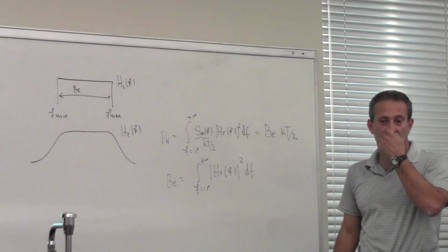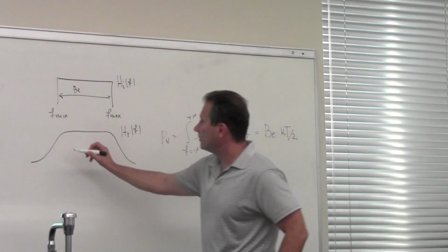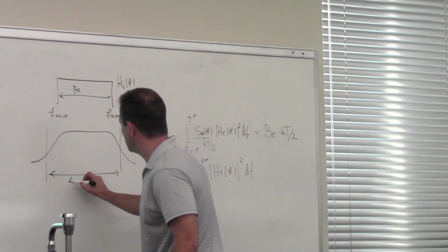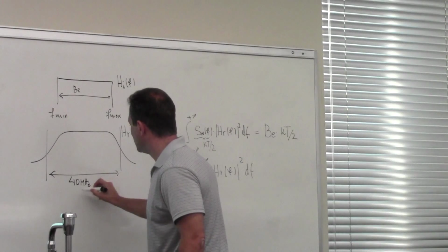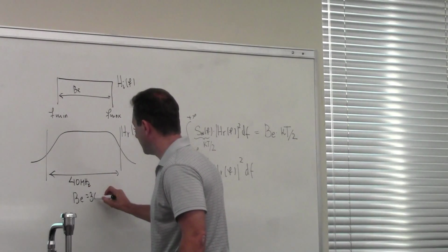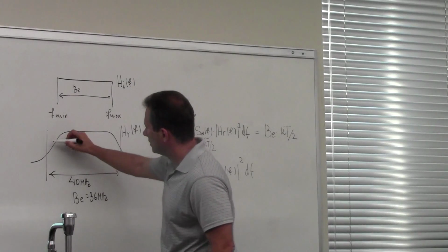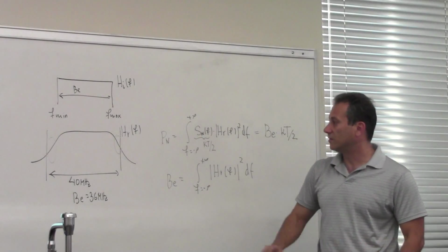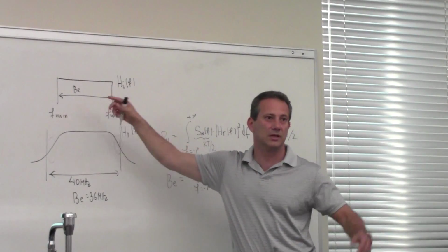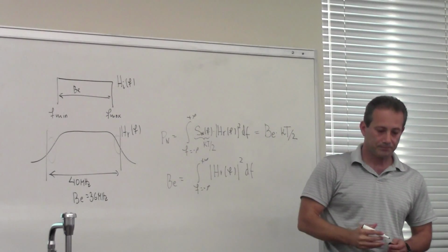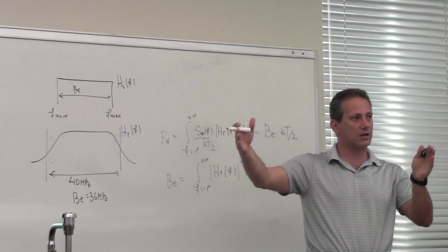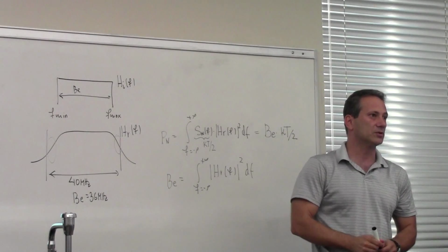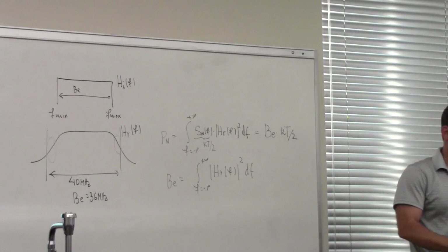And we can say, for example, that's why a lot of times you say the width of your transponder is, let's say, 40 megahertz, but your equivalent bandwidth is 36 megahertz. Why? Because there's a reduction in the noise in these skirts. So it is equivalent as if you were to have a box that is only 36 megahertz wide. So you reserve 40 megahertz for this channel, but because that includes the skirts of your filter, your equivalent noise bandwidth is somewhat smaller for noise calculation purposes.